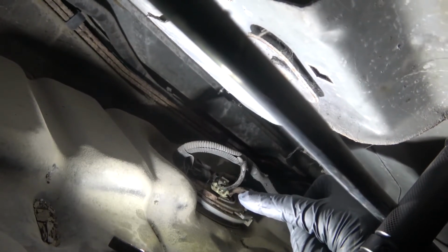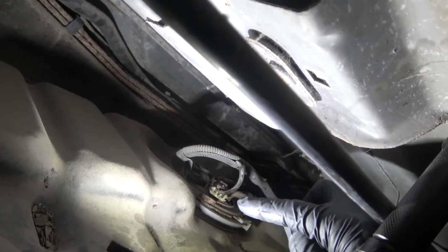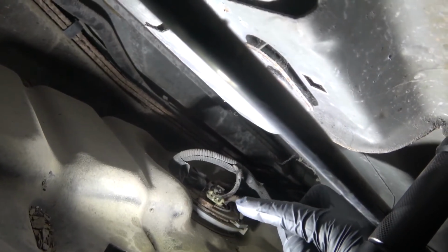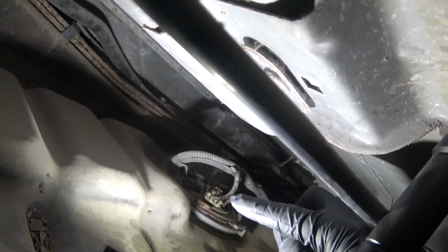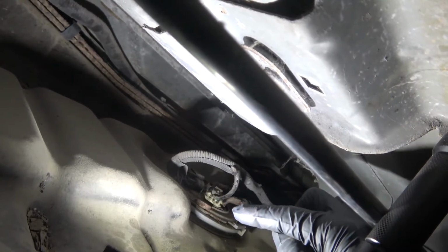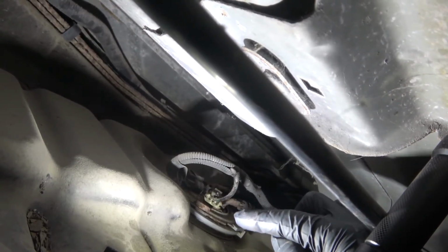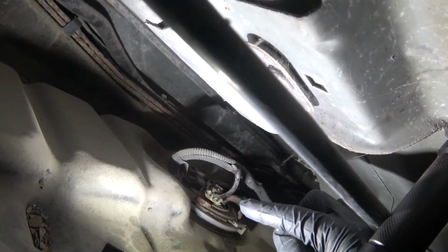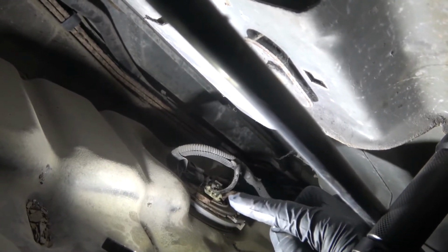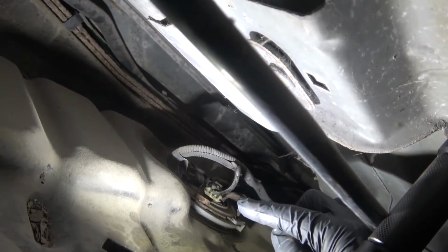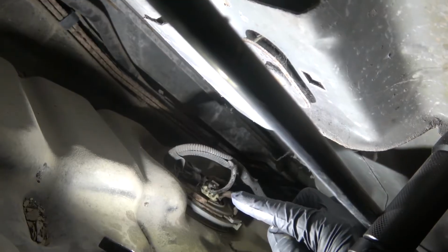I'm going to back probe all those 3 wires, and then we're gonna use our lab scope to check the wiring of the sensor. We should have 5 volt on one of these wires, ground, and then signal. If the wiring checks out okay, then we're gonna go ahead and replace the sensor. I'm pretty sure the sensor is bad, but we're not just gonna replace the sensor. We have to test the wiring first, okay? I'm gonna get all these wires back probed, and then I'll bring you guys back up.